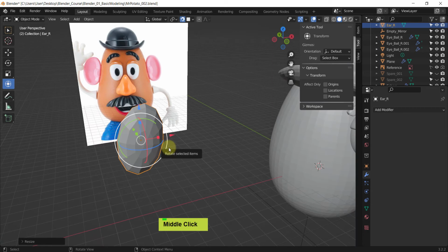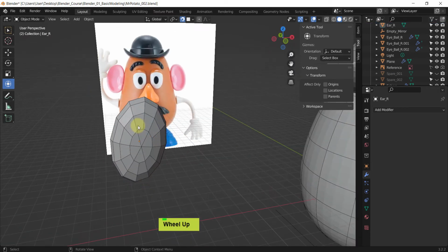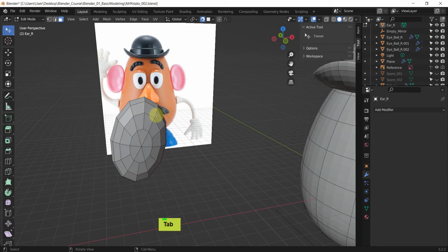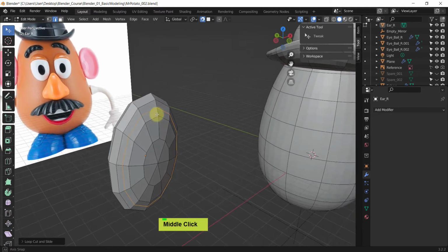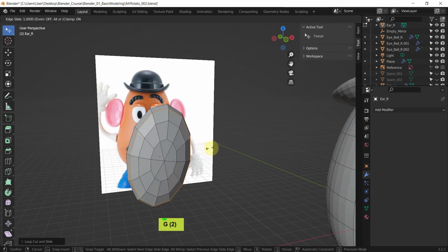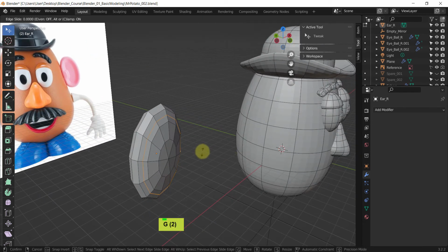And what we want to create is the inside rim. Now for that, Alt E, I will insert another edge that's going through here. So edge mode, number 2, and Control R, and click in this edge. It is fine. Maybe I will, yeah, that's fine. Actually, we can glide it a bit. Oh, we have a snap. All right, that's causing a problem. So Alt Tab, snap is on, and GG to slide it. Yes, now it's much better.